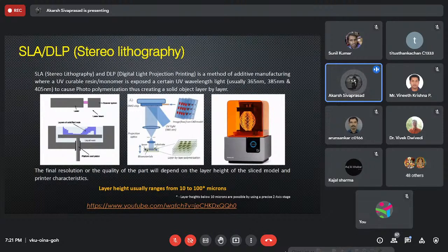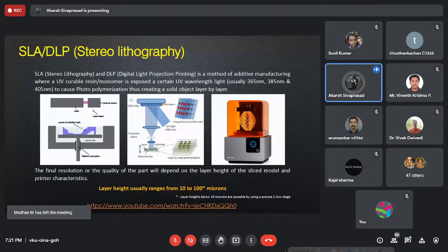A 100 by 100 millimeter part is going to take quite a bit longer than the previous time. What the second system does, instead of tracing its path, is shine the exact image all at once. It took the complexity of the XY geometry completely out of the equation. So you can rapidly image the same stack without tracing or requiring scanning optics or a galvanometer to do that.